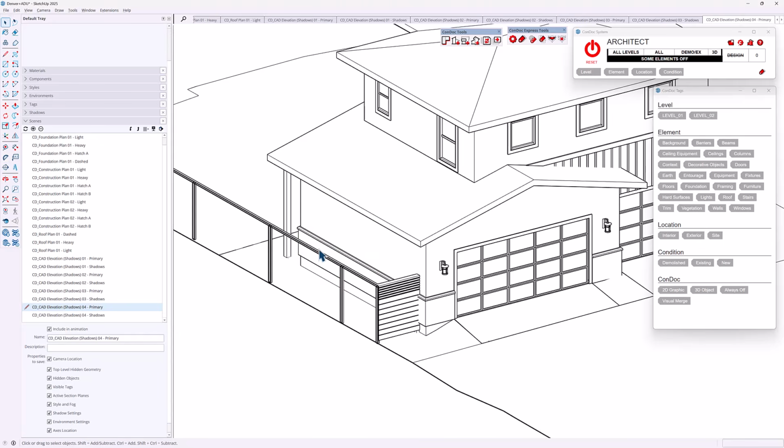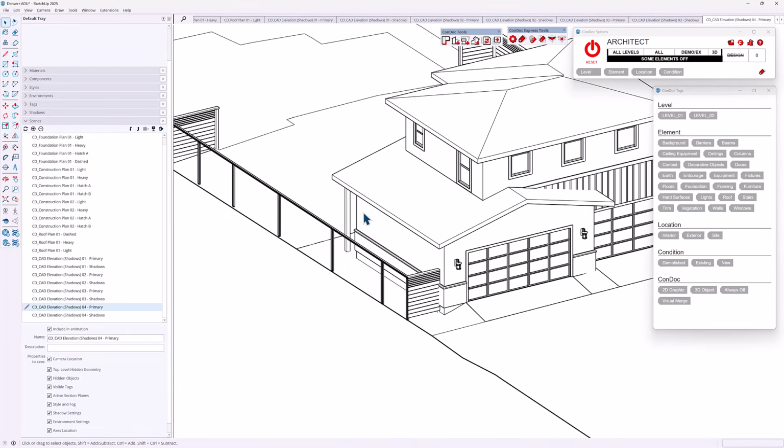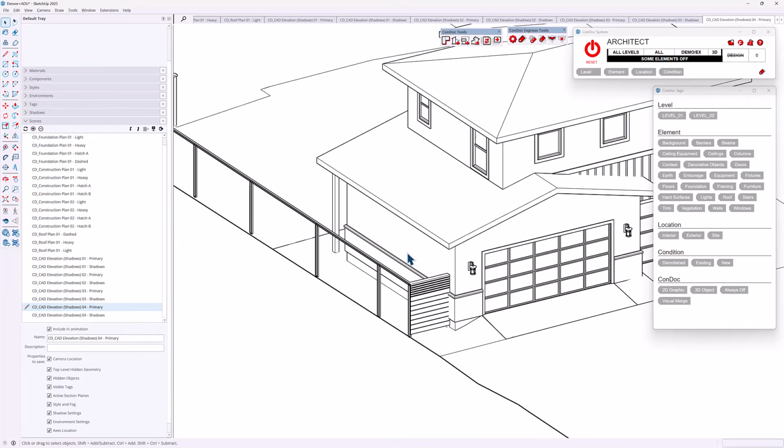That's just by design for the elevation tool, because typically you wouldn't want to section right there if you're creating an elevation. The section tool does cut right where you click it. The elevation tool bounces off 5 feet, and that dimension is adjustable in the configurator, but it's impossible to predict what's going to be the right distance. If it was only 1 foot, I'd be hitting the soffit, and it just so happens I hit the fence, but that's okay. Check this out.